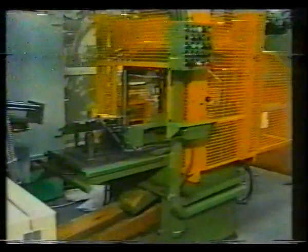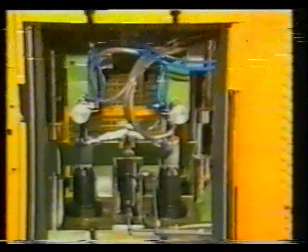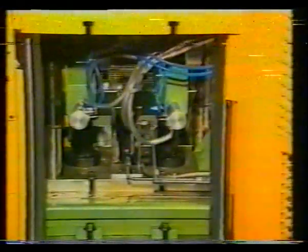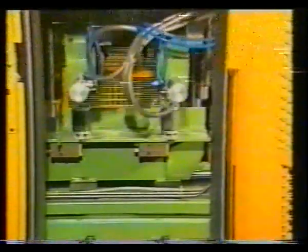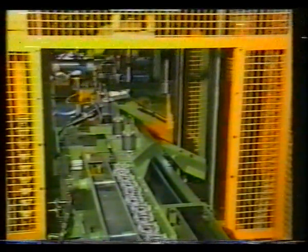The sliding table then moves into the trimming press. When the press closes, first the mandrel is ejected, and then the gating is trimmed off. A special cylinder makes sure that the gating is extracted. An additional dropout detector is also provided. The new cycle is only started if the system has been cleared. In other words, when the gating has left the system.